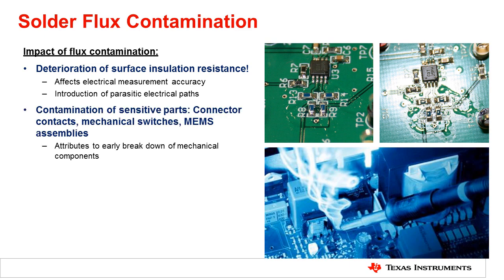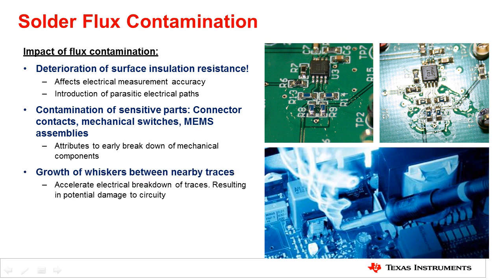Flux may contaminate sensitive components like switches, microelectromechanical systems, MEMS, and contactors. Over long-term operation, mechanical components may break down more quickly. Lastly, whiskers may form between traces, resulting in potential shorts or unwanted electrical paths. In some cases, whiskers may lead to damage to the integrated circuit and/or PCB.